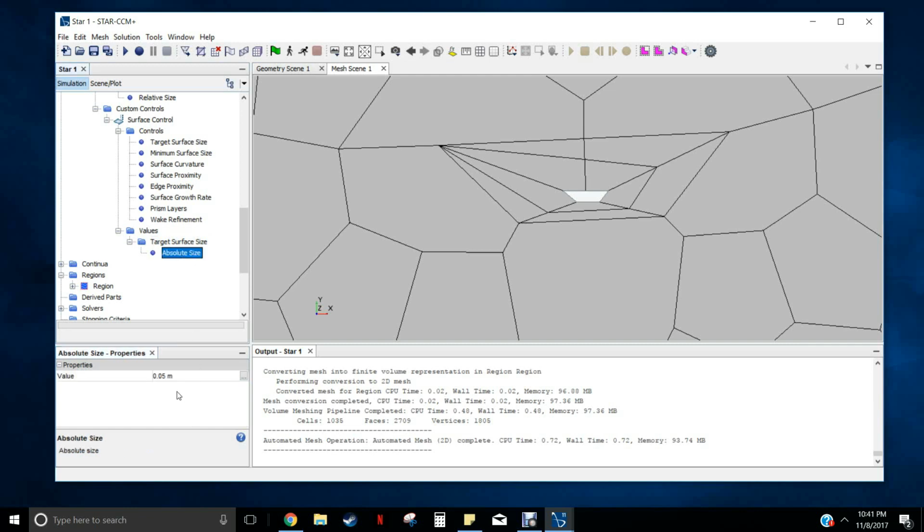And then if we click down here again, I'm going to make this 0.00314159. This is essentially the correct size so that you're going to have 100 divisions all the way around the circle. That's just calculating with a 0.1 diameter cylinder, how many divisions you'd have to make. So you can hit enter.